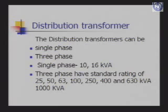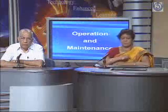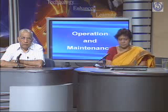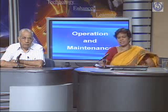But in the HVDS system, which yesterday you covered, and you are providing to reduce the losses as well as to make the supply reliable, do you think that transformers of more than 25 kVA would be required? No, in HVDS the basic concept is small capacity transformers.